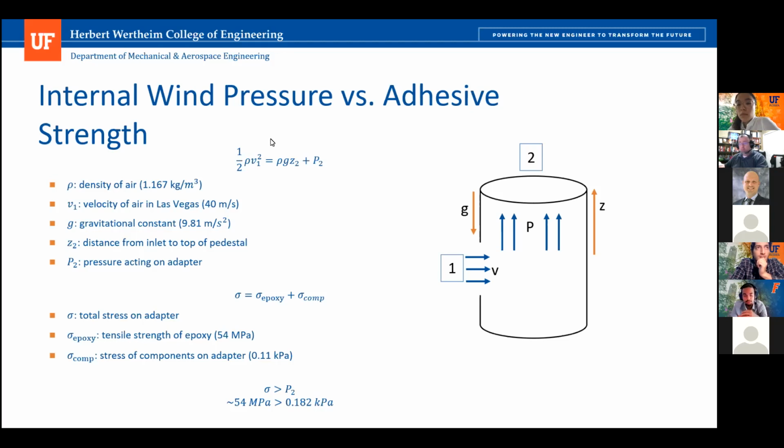Yeah, so each module is going to have 8 foot of spacing and be placed in that row, kind of a radial staggered pattern. We did that 8 foot based on the width of a truck, and that's how we determined what the spacing would be. And that's a straight line 8 foot, or is it a zigzag? No, that would align radially from the tower towards the outside. Okay, good. Thank you. That's all the questions I had. I think it's a great presentation. Thank you so much.